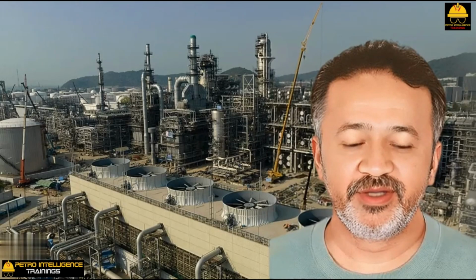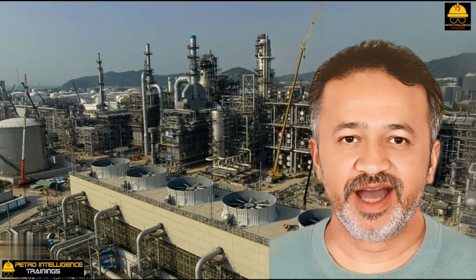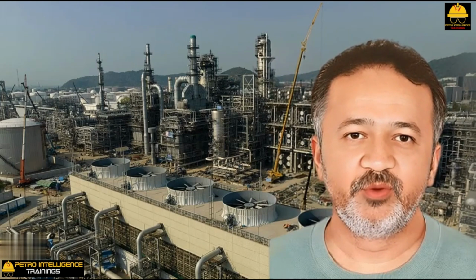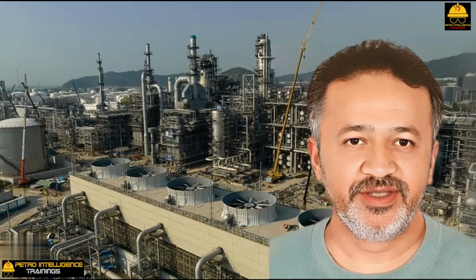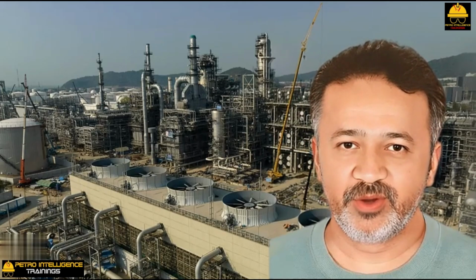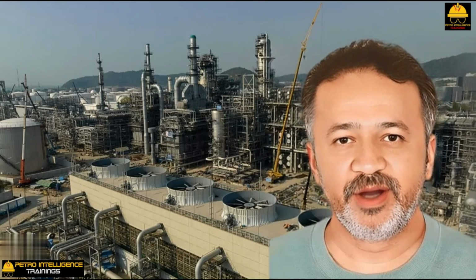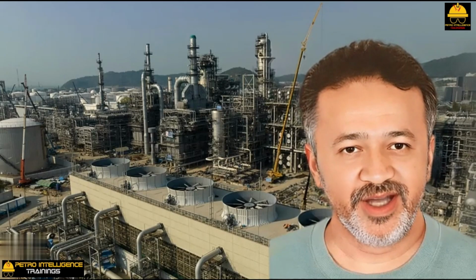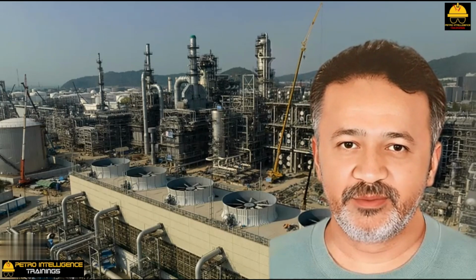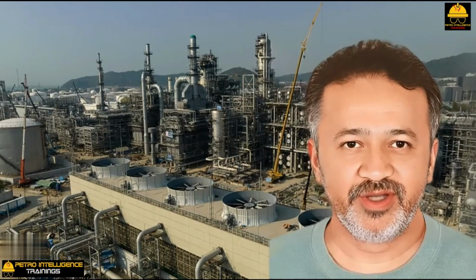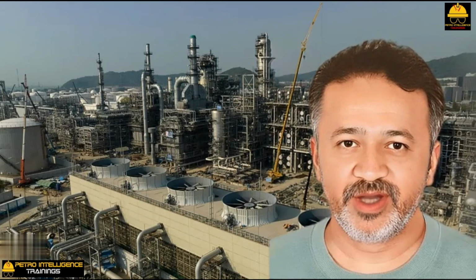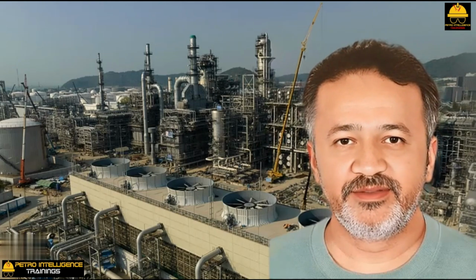Air cooler fan alignment. For forced draft fans, I have sometimes seen that the fan assembly gets slightly out of true vertical alignment. One side of the fan is running a little higher than the other. The consequences of this misalignment will be to increase the clearance between the fan blade tip and the inside of the shroud by perhaps a few inches. This increased blade-to-shroud clearance will promote air recirculation from the discharge of the fan back to the bottom of the shroud. The net result is a reduction in the airflow through the fin tube bundle. The problem can be corrected by realigning the fan assembly.